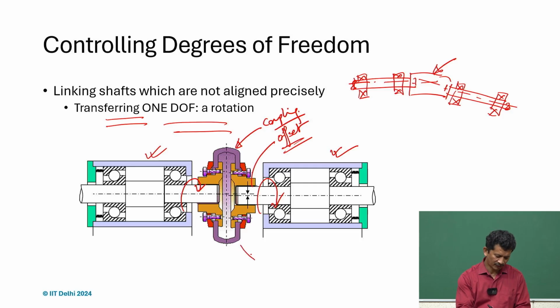So, what we see here is actually a flexible coupling, and in many rugged, heavy applications, we might not be looking at precision, and then we can simply use some elastomers or rubbers and some kind of tubing where it can flex easily, and then we can clamp it and it works. So, it does all of them, and the rotational constraint is there, but because it is flexible in that direction, it is very difficult to get precision in this case.